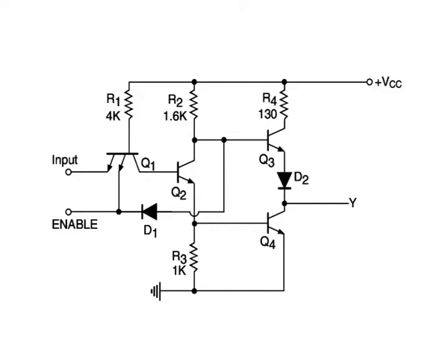Tri-state gate. A tri-state gate has three output states, namely the logic low state, the logic high state and the high impedance state. An external enable input decides whether the logic gate works according to the truth table or is in the high impedance state. Figure shows the typical internal schematic of a tri-state inverter with an active high enable input.